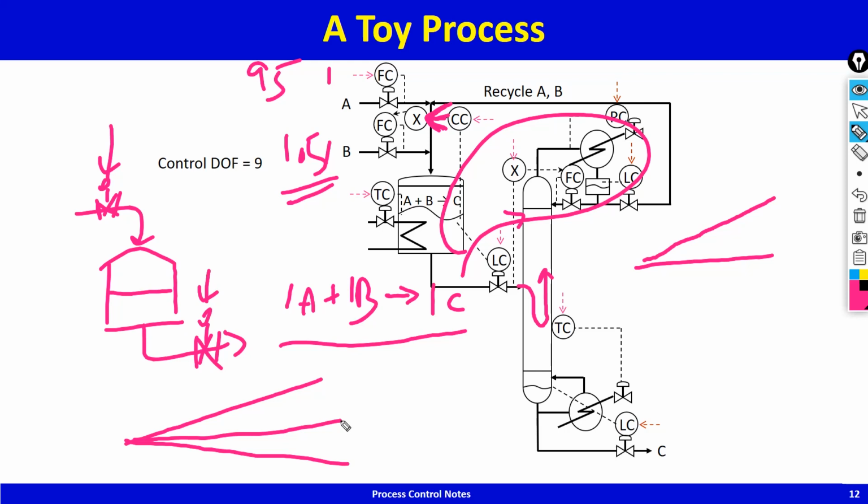So to stabilize this system, what do we do? In the previous example, we took flow in as independent and put a level controller that manipulates flow out. Here what we'll do is put a level controller that manipulates flow in. So now in this case, flow out is independent, and the inventory that was drifting, which is the level here, that drift in the level is an indication of flow mismatch. So you measure the level and you manipulate the inflow or the outflow. In this case we are manipulating the inflow, so that in minus out is exactly 0.